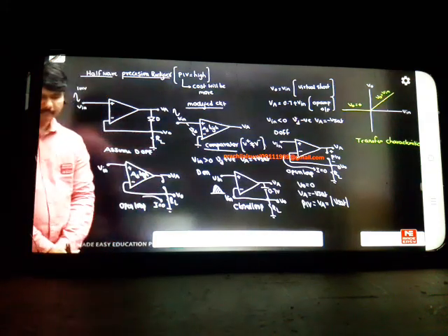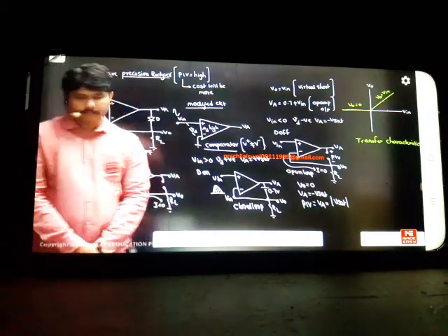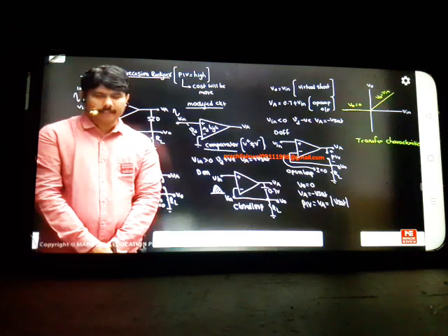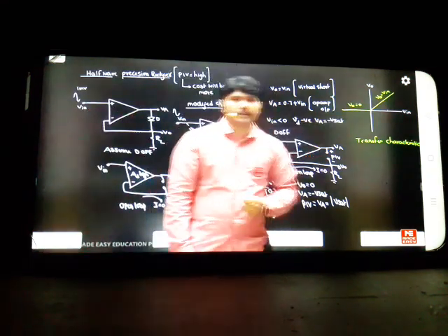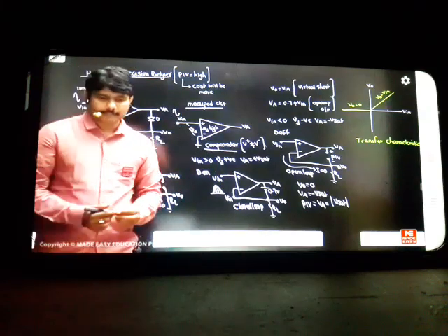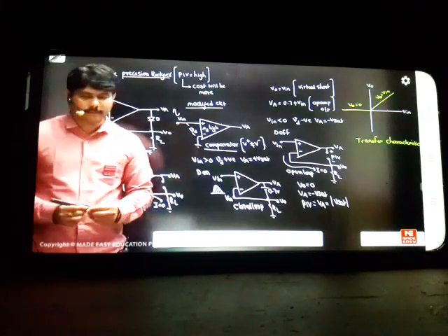Yes, Roy, if the diode is upward, you'll get a negative graph. The transfer characteristics will come, output equal to input here. The positive cycle will be 0 for it. That is the only thing that will happen. So just a small note I'll give for the problem.